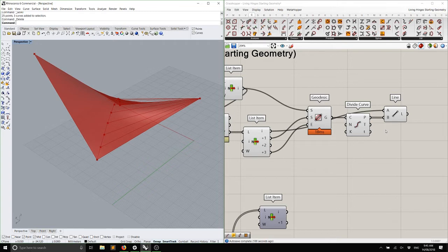Your geodesic is going to be generated there, like so, but then the point that you're going to generate that to is that point. The reason it's flat is because you're using the support points, not the center point. I'm not quite sure why in this shape the curve is under the surface. Because the quality of the surface you're using is set to the worst quality possible.